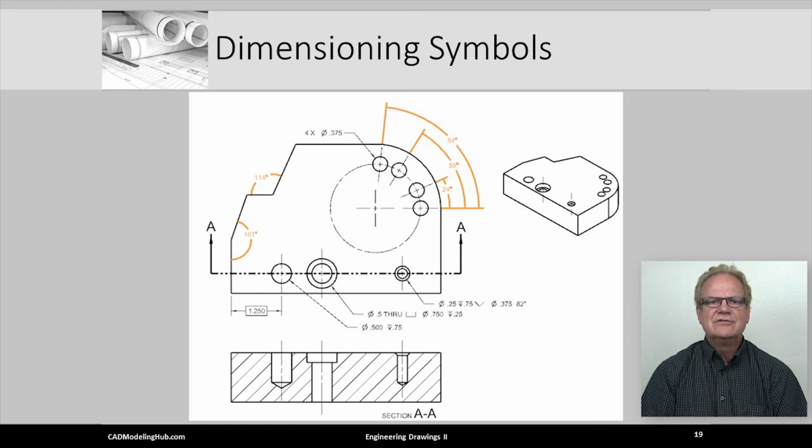Also, it is generally considered bad practice to place dimensions on the part, as was done with the 161 degree angular dimension. To avoid this, we could have extended the vertical object line with a vertical extension line and defined the edge of the angled surface using an acute angle.